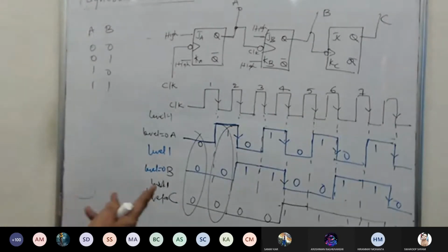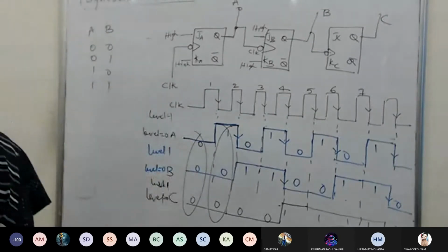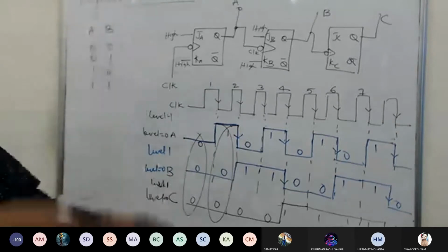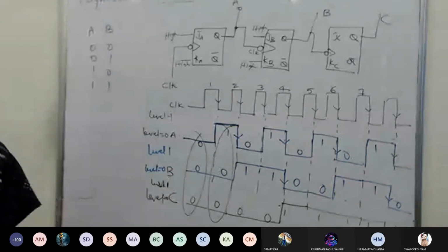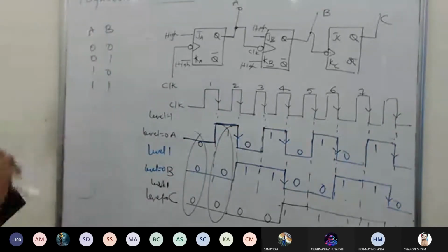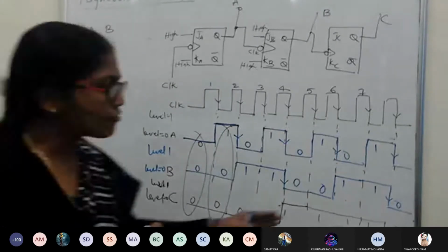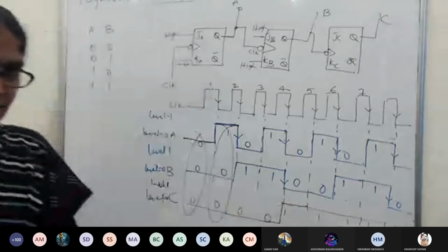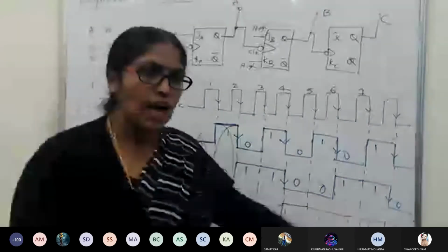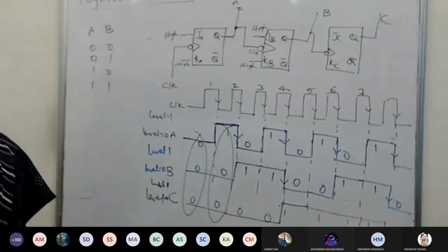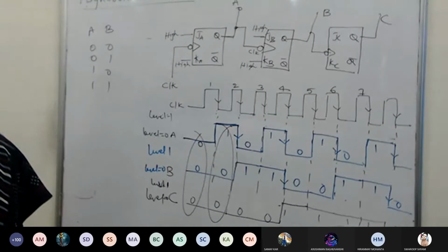Whereas in your synchronous counter, what is happening? Clock pulse will be the main thing. Afterwards, everybody has to follow. Right. Now, there was an issue here. Sometimes it so happens that after generating my 8 states, that means my count is over, I have to restart. Carefully understand. These are not forever continuously done.